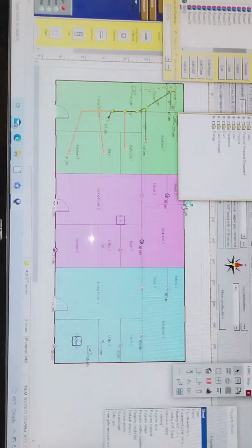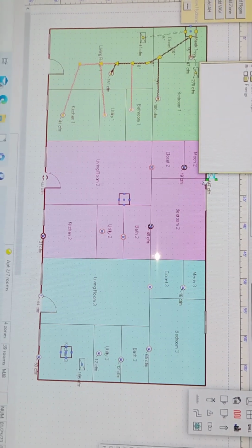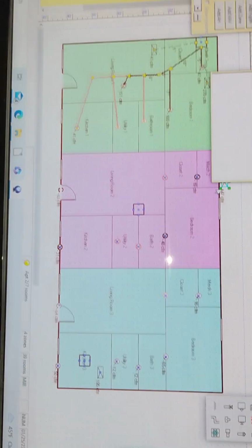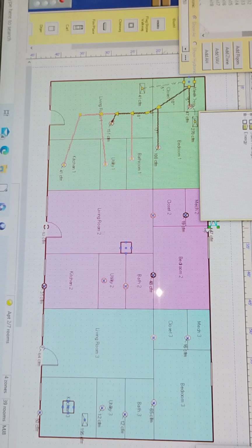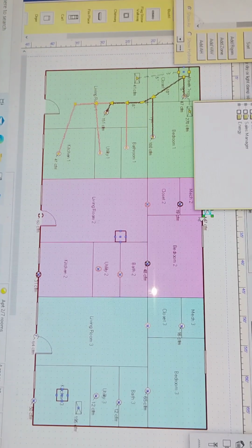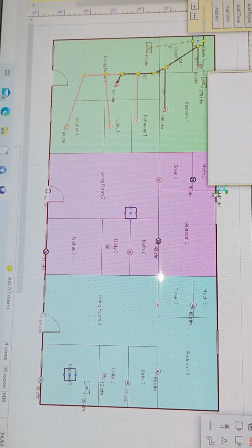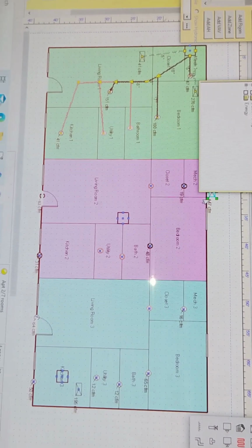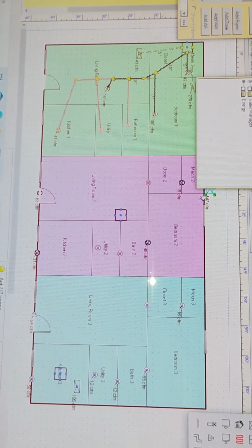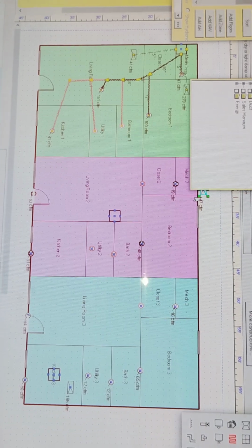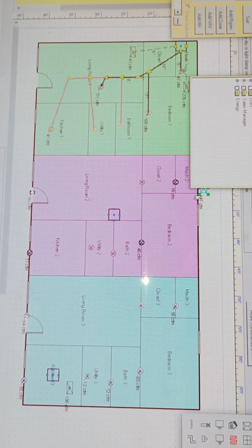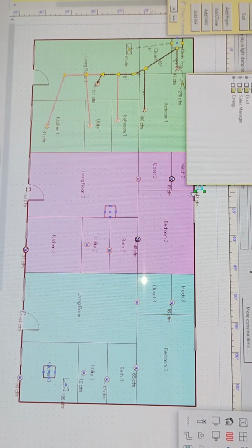Now, some of these loads will come out in that range. However, some of these loads, like you can see on this one without adding the appliances and stuff, this thinks that it's less than a ton for 660 square feet and would probably be close to correct. Again, we've got to add in our washer, our dryer, our kitchen equipment, our hood for our exhaust on our kitchen, our bathroom exhaust. All of that stuff will add loads to it.